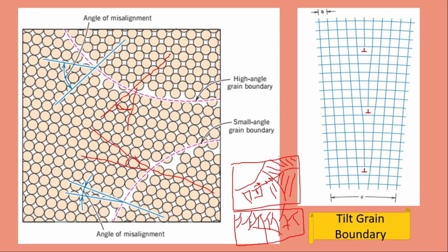And we can increase the size of the grain if we increase the temperature and allow it to cool down slowly. So there are methods called heat treatment techniques, which we'll study in this subject in chapter number 9, by which we can control the grain size. Depending upon our requirement, if we want a material to be malleable or ductile, we want a coarse grain structure. If we want that to be hard and with a high strength, we will make a fine grain structure. So we'll perform the heat treatment operations accordingly.